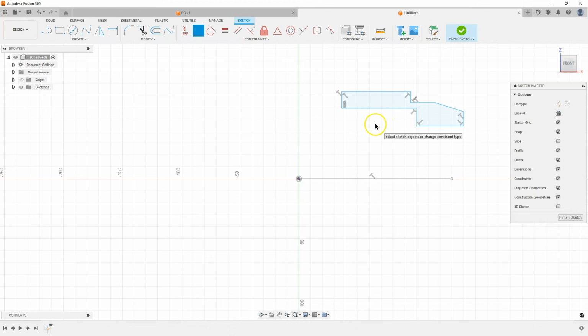Okay, and then let's add dimensions. But first let's learn how to determine the diameter dimension. Select Sketch Dimension, and to add a diameter dimension, select the line defining the axis of symmetry, then select the outer line of the dimensioned diameter. It can also be a point.